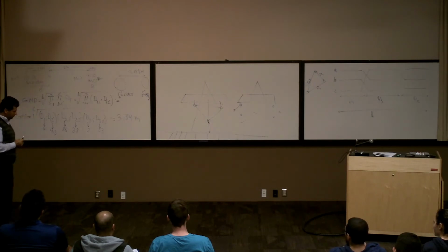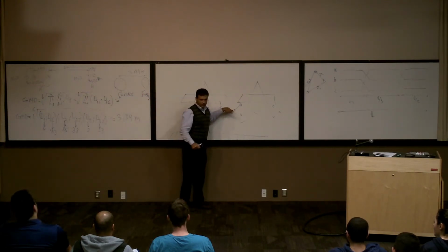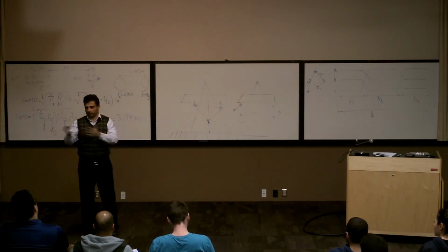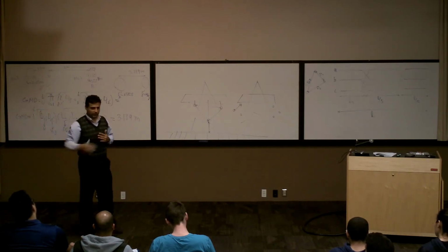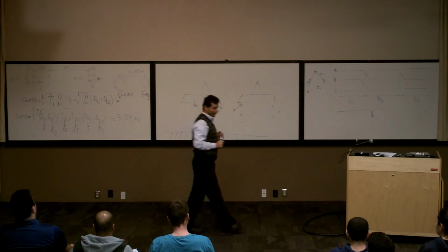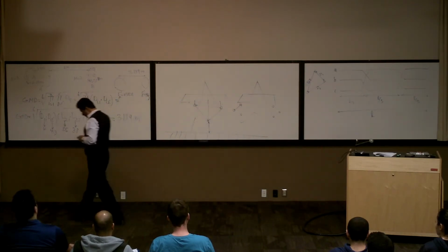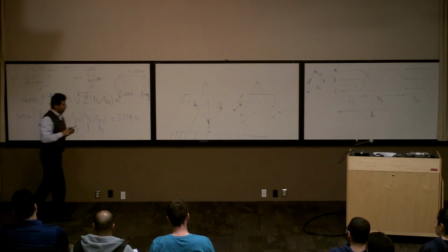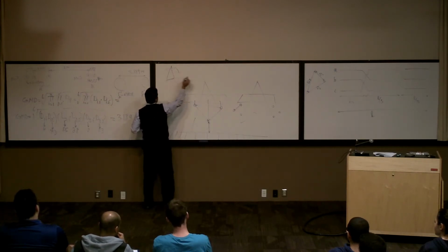Now, to solve the problem, to keep all the conductors here and keep the system balanced, we do the transposition. We rotate it: up, middle, down, up, middle, down. This way we can fix this problem and make the system balanced. Now we're going to calculate the inductance for this system. Another thing about transmission lines is very critical. This design is very critical. When you have two towers, you have two towers here.